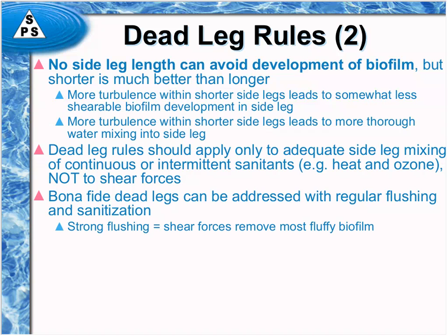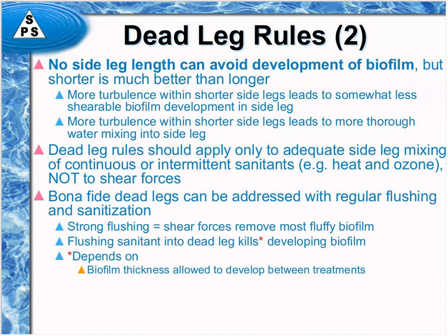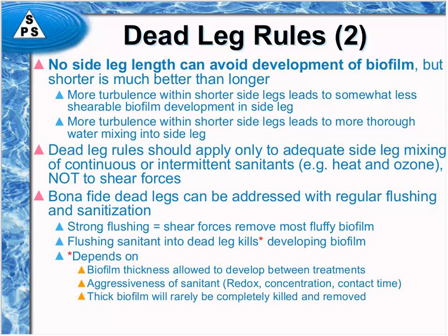You actually create flow in it. And those strong flushing forces will create the shear force that will shear off most of the fluffiness of the biofilm, leaving the tenacious part behind. It will also allow you to flush sanitant into that dead leg, which has at least the opportunity to kill the developing biofilm. But that killing, and I have a whole webinar based upon sanitization, but that killing is based upon the thickness of that biofilm that's been allowed to develop between treatments and how aggressive the sanitizer condition is, which is related to its oxidation potential and concentration and contact time.